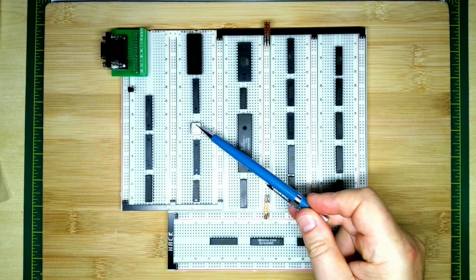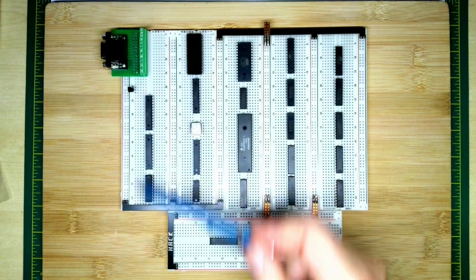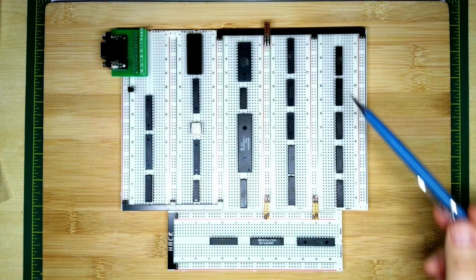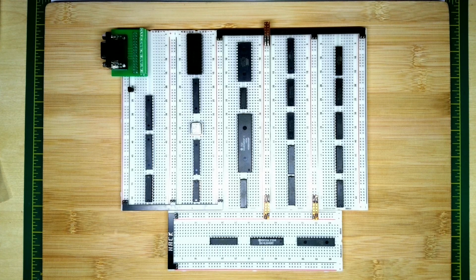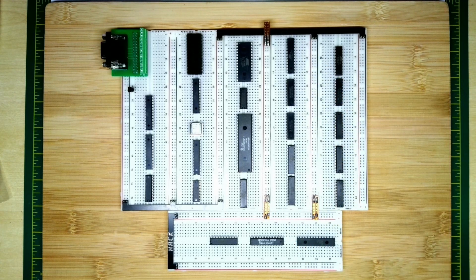And then we've got a 25 megahertz oscillator here which provides the dot clock necessary for VGA output. And then we've got lots of PLDs, latches and other general logic that we need to support all of that. So we wired up these breadboard buddies for the power rails and these various connectors, and one of the things we need to do now is to check all of the chip labels and actually put them on.